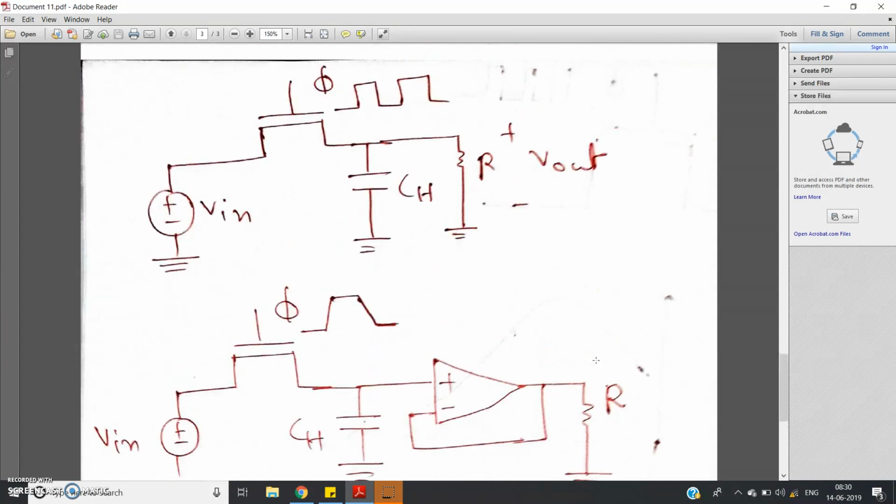One more thing, this kind of concept is very important. Here I have drawn a square pulse with exactly 0 rise time and 0 fall time, but in practice that is not possible. If you simulate in Cadence, as you might have done in a VLSI lab experiment, we give some small rise time and fall time. So in practice, if we implement a square pulse, always try to give a square pulse that looks more practical, with certain rise time and fall time. This is also a very important point.